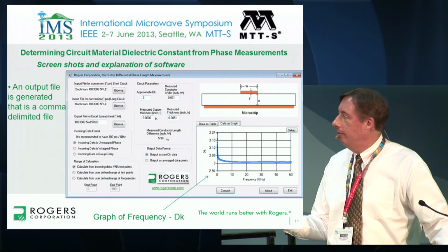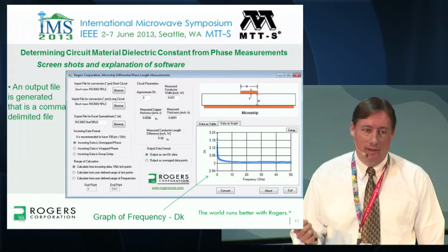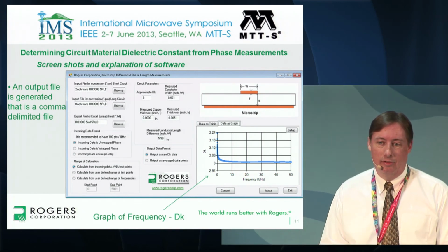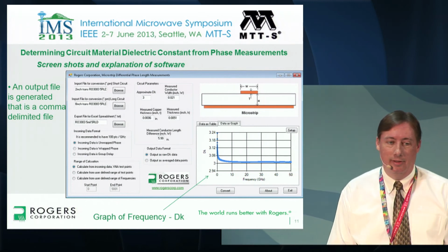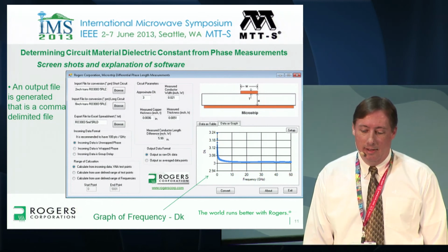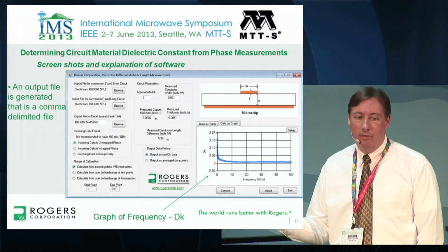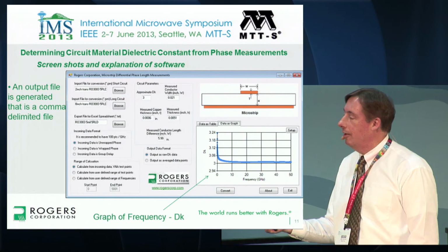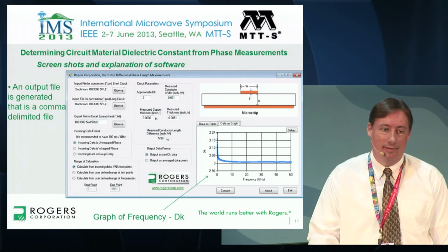Material scientists know this phenomenon pretty well: the dielectric constant versus frequency becomes nonlinear in a certain area, and that really has to do with these moments of relaxation. So this nonlinear area is actually valid, it's true, it's there, it's shown. But what I was talking about earlier, the shorter circuit having less accuracy at lower frequencies, really has to do with these numbers going up the y-axis and blowing up because it's not acting like a transmission line.